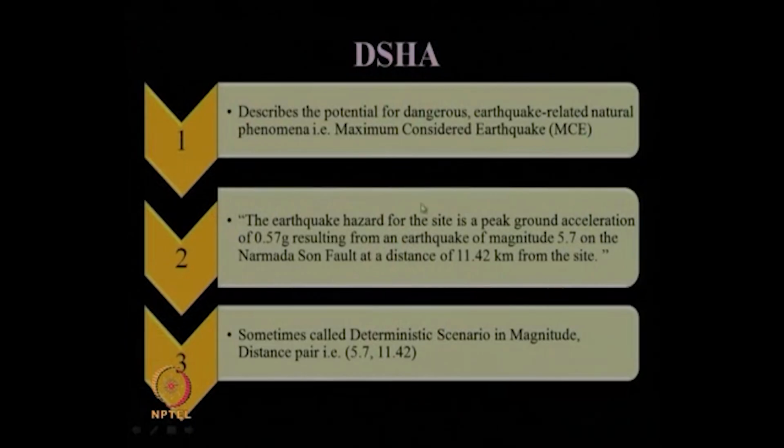Then we have seen from DSHA how we mention MCE, maximum credible earthquake or maximum considered earthquake, as a combination of magnitude and distance from one particular site with respect to the fault distance, and the magnitude which is going to occur as per this deterministic seismic hazard analysis.